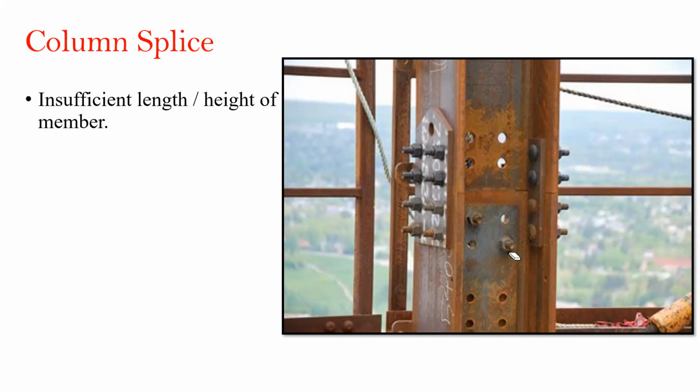And one more thing you have to remember is, depending upon the requirement, you are also going to provide the splice plate onto the web of the I section. This portion is the web. This entire portion is the web. So onto the web of the section, you are also going to provide the splice connection. When you provide the splice connection on the web, it is called web splicing.